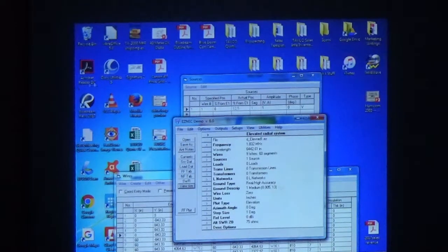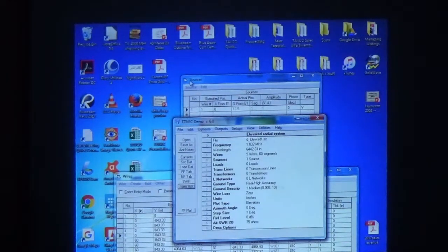If you've got an inverted V, and say it's at 40 feet, and you got 20 feet at each end, and you got a tree next to it, and it's over a house, and there's a tree on the other side, is there a way to tell how that affects the radiation pattern? Not exactly, because you cannot model trees. People in like the Antenna Compendium and stuff have modeled cars, but it's wireframe modeling. They just sort of wire the outline. You just have to give a reasonable representation. You can't do that for a house or a car.